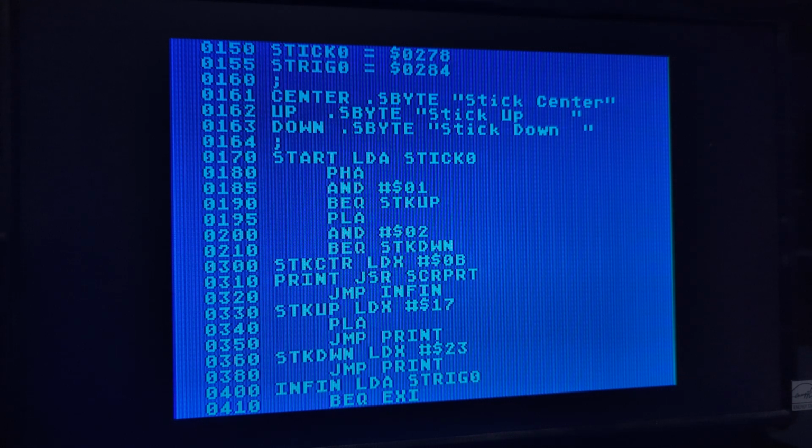It doesn't change the value in the accumulator. And that sort of sounds like a good thing. Well, then I don't have to store any variables, because I can do that bit comparison. It does the masking the same way, and then I don't have to worry about storing the value in the accumulator somewhere, because it never changes.